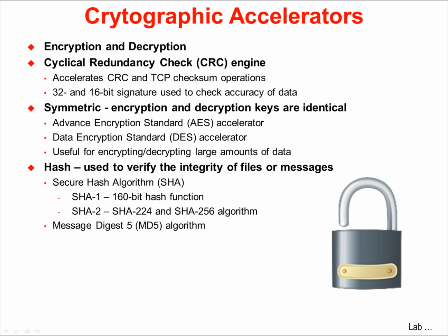Cryptographic accelerators are implemented in hardware in Tiva TM4C1294XL devices. These accelerators include a CRC engine supporting both 32 and 16-bit calculations, a symmetric encryption engine supporting both AES or DES standard in hardware, and a hash-based authentication capability using SHA and MD5 algorithms.